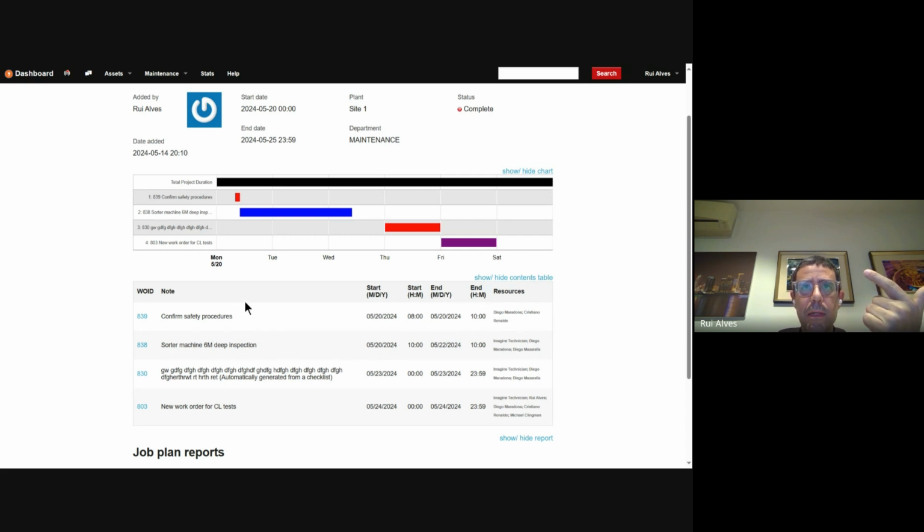So as you are planning through the shutdown, where you're at over here, you not only know that the date to finish has passed, but there is no guarantee that the job is done. Like I mentioned, there is no feedback in here unless we put this strikeout marking. So you'll know whether you've passed the date, or you're on the date, or maybe you're before the date, but the technician has already set this as complete. You'll be able to see it here and say, oh okay, I planned it for 2 days, but the guy already finished the job. It's been a day and a half.